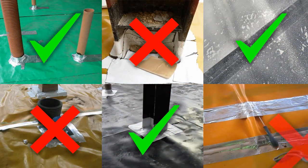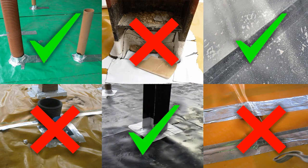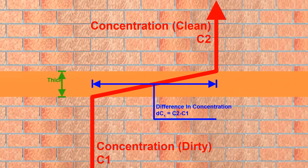While there are some obvious common sense considerations here, such as ensuring there are no gaps or punctures in the material and all pipes and structural elements are properly sealed, there are also some less apparent aspects to bear in mind. As we've discussed already, the thickness of the membrane is an important factor regarding vapour permeability, and this also means that any factors that may affect the thickness are important.